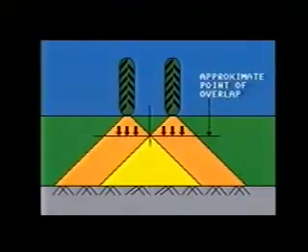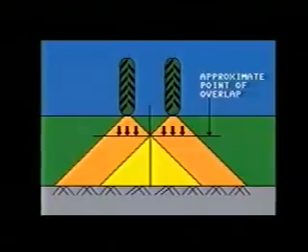When a vehicular load comes on a pavement surface, the load stresses are distributed through different layers and transferred through a wider area of the subgrade. Due to the ability to distribute the load over larger area, the stress gets decreased on the lower layers and is maximum at the point of overlap.